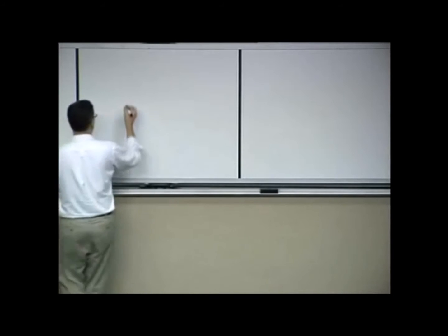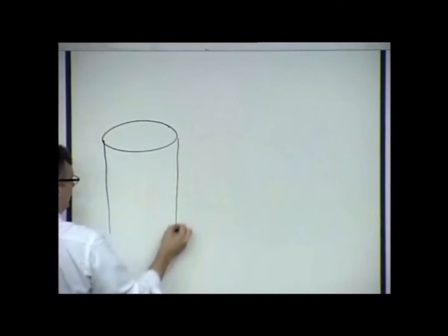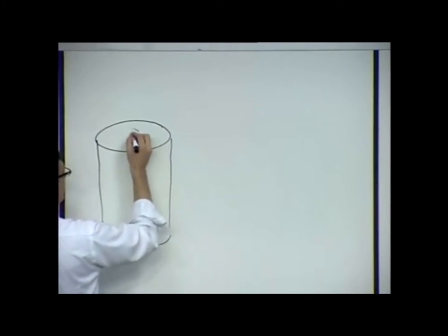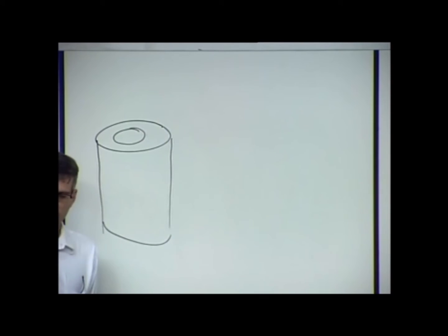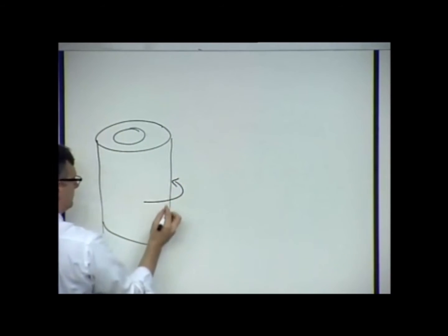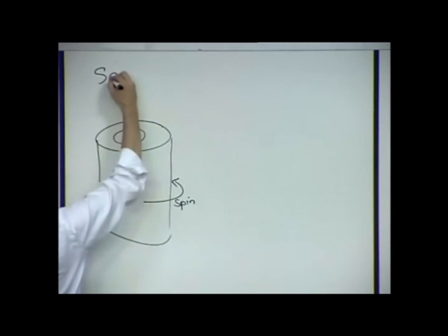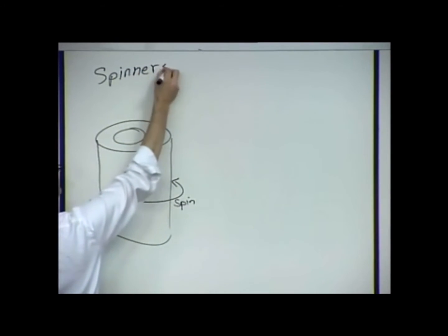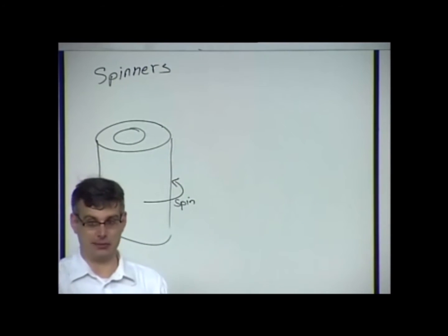And so one of the simplest ways to do that is to make a drum-shaped satellite. You plaster it with solar panels, and when you launch this from your rocket, when you deploy this payload, you give it a twist. You spin it. In fact, these are colloquially known as spinners in the satellite industry. Or, if you want to be official, single-axis stabilized.